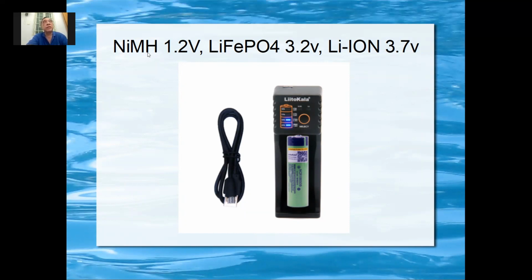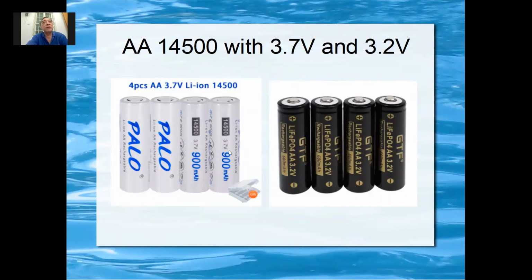It can also charge a nickel metal hydride battery. And this one can charge a 18650 or the AA battery or AAA battery. You can charge any size battery and any voltage. Okay, of course you cannot charge the USB type of battery. That one is not. You need USB to charge. You cannot use this one to charge. This one is meant for this type of battery. Okay, so when you buy, look at the voltage. Look at the voltage.